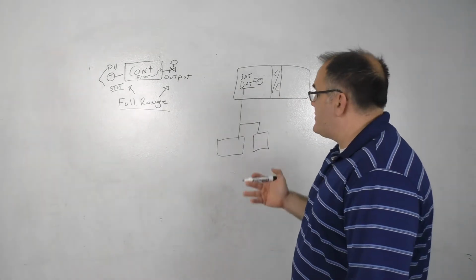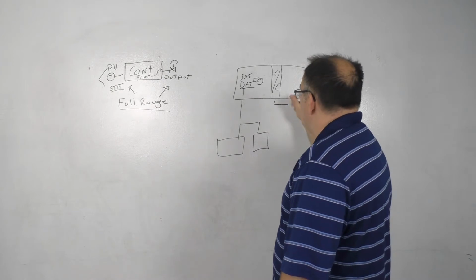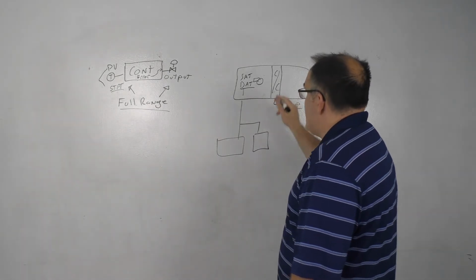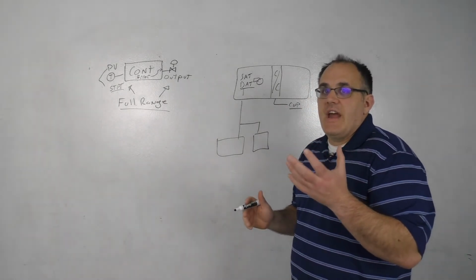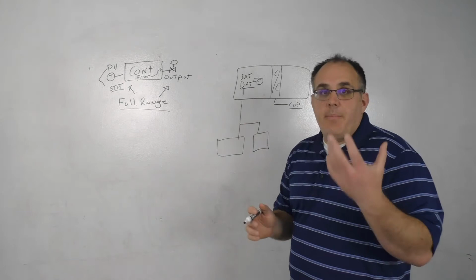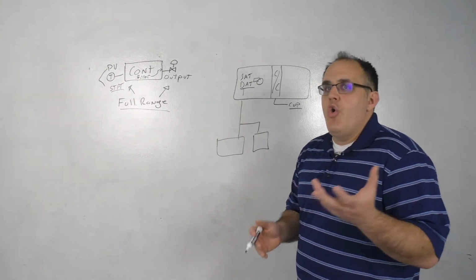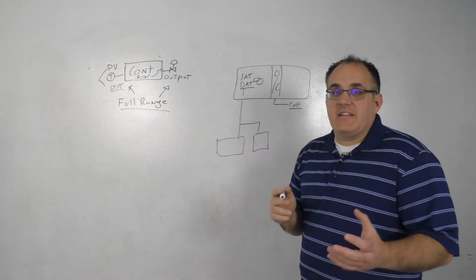And the purpose around resetting the discharge air is that upstream of this cooling coil is your central utility plant. If we back up our discharge air temperature set point, meaning we increase it maybe from 55 to 65, that makes the coil less likely to open.